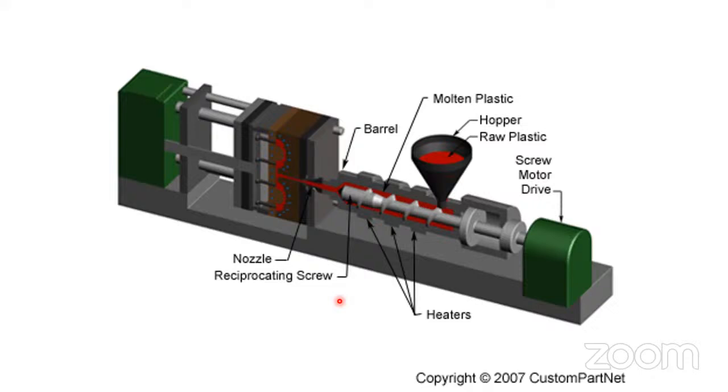I think in both cases the screw is rotating, and due to friction that is converting into heat energy, melting. No, you are right. By friction, heat energy is involved, and by shearing action it helps to melt the material. But when the screw comes backward, that time only it rotates. Because by rotation, it is coming back up to this place.